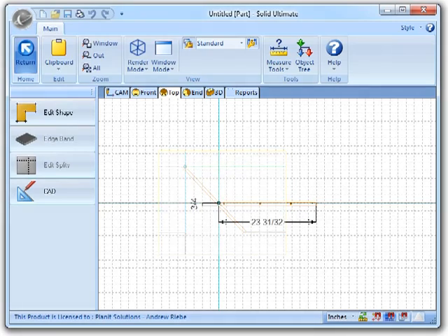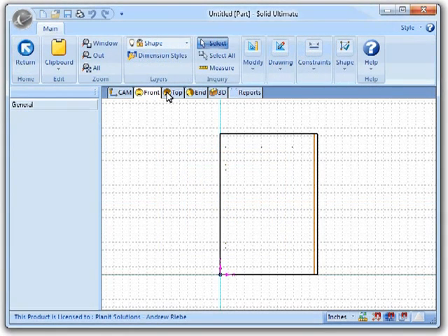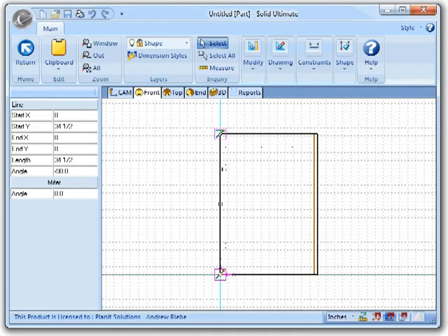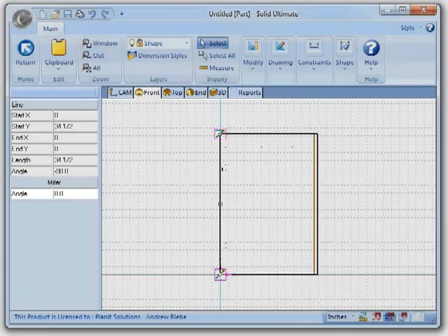To easily set a mitered edge, you just go to the Shape Editor and select an element that represents the edge you want to miter and change the miter angle value here.